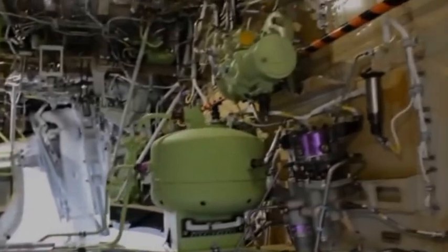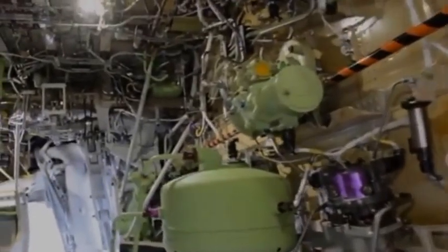It is also very important during the exterior walk around just before the flight that we make sure the main wheel well and nose wheel well lights are operational, especially for night flights. If you get a problem with the landing gear system at night and want to view from the viewing ports to check whether the landing gears are fully down and locked, we need to turn on the main wheel well lights and the nose wheel well light to have a better view of those markings.